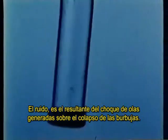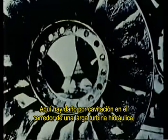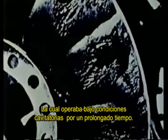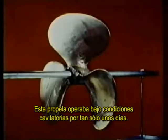The noise is a result of shock waves generated upon bubble collapse. The pressures associated with collapse are high enough to cause failure of metals. Here is cavitation damage on the runner of a large hydraulic turbine, which operated under cavitating conditions for an extended period of time. This propeller operated under cavitating conditions for only a few days.